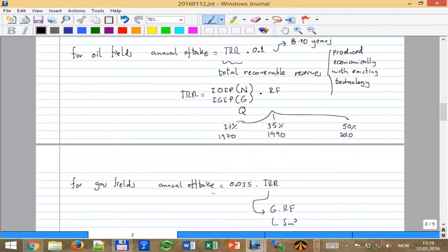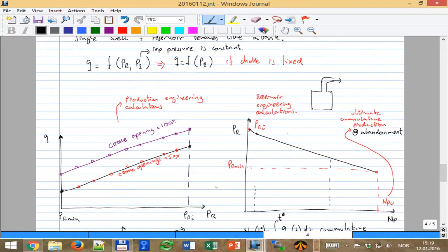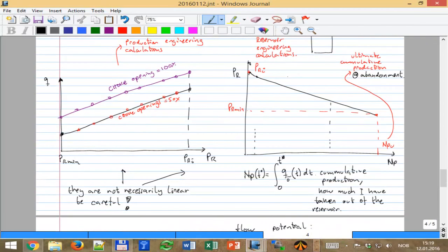This trend that I showed you says that if I have a very high reservoir pressure, I will be able to produce a high flow rate. If I have a very low reservoir pressure, then the flow rate will be much less. And all in between, it follows a trend. We don't care too much at this point what the trend is. You will see later the idea that you can generate these curves yourself and know more or less how to calculate them. Also, one warning that I told you is that it depends on the choke in the system, and on the opening of the choke. If it's closed or halfway open, then you have more resistance to flow, and the flow rate will be less compared to when it is fully open.